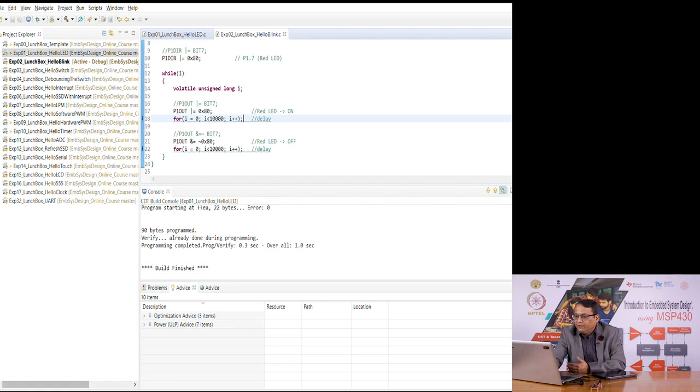Once you get out of that loop, you toggle the value. Now, here we have done an XOR of the original value with the inverted value. That is what we have done here, and this toggles, this makes the LED 0, and then again we delay. So, we have another same repeat of delay function, and then this is the complete while loop. So, it is going to go through that writing 1, delay, writing 0, delay, and it is going to do this infinitely.